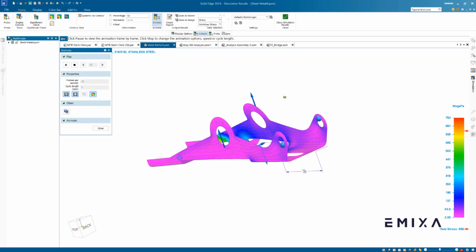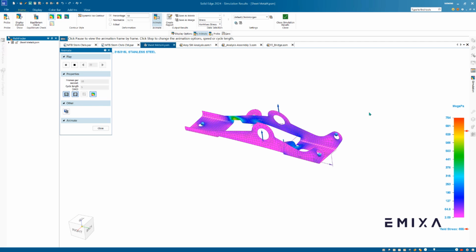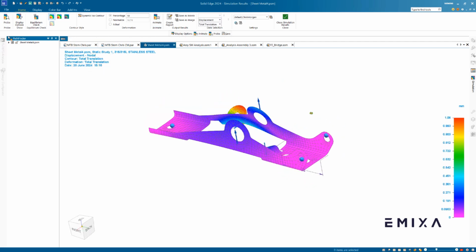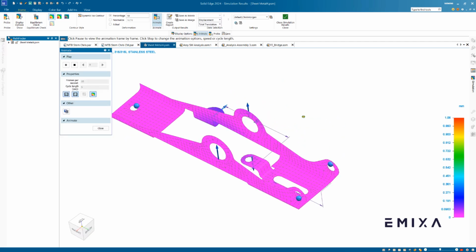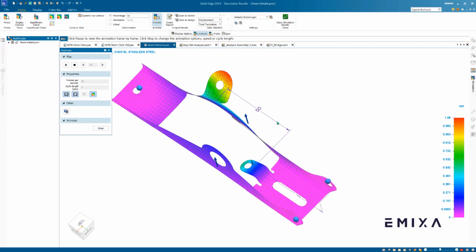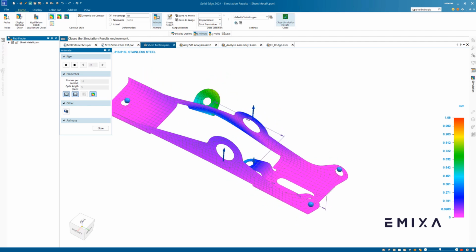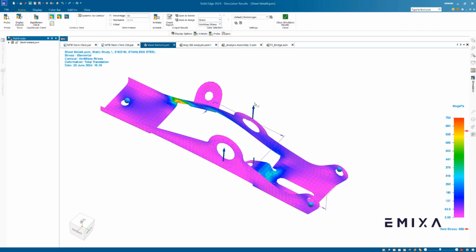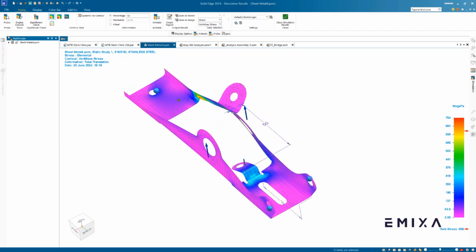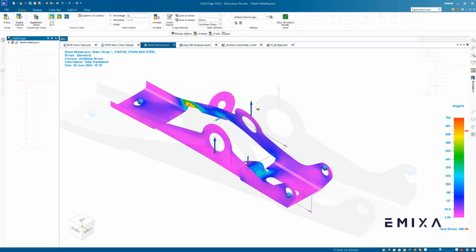And that's then going to show our stress. So we've got a high stress point. We can see our red arrow on there, meaning that bit's going to have failed. And we can choose to animate that, show where that's going to move. So we're seeing this as displacement on here. Obviously we're showing this as a kind of ratio. It's actually moving more in the video than it really would. So that little point is causing the problem on there.